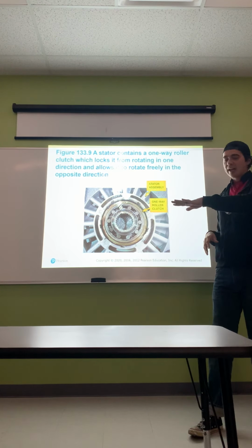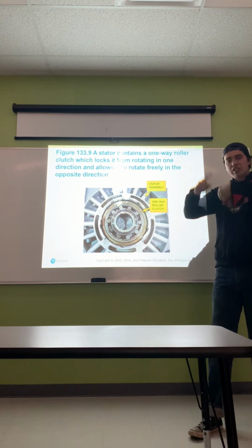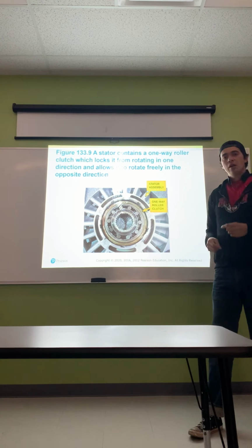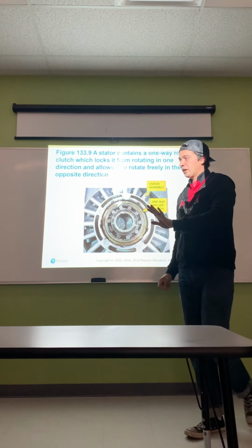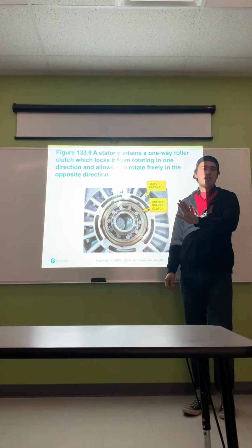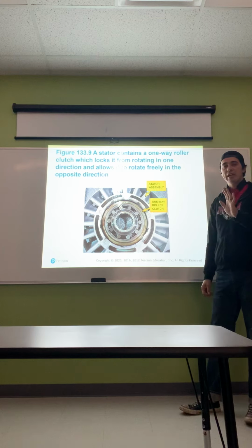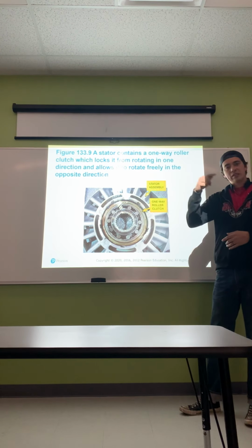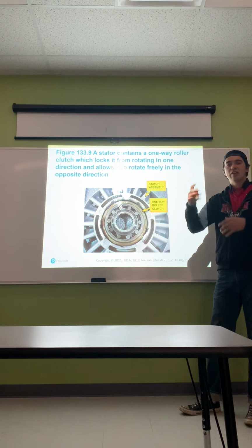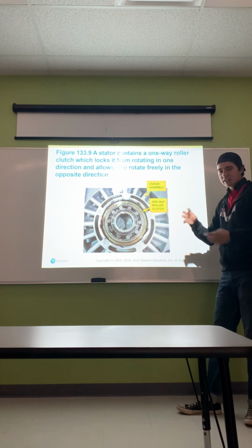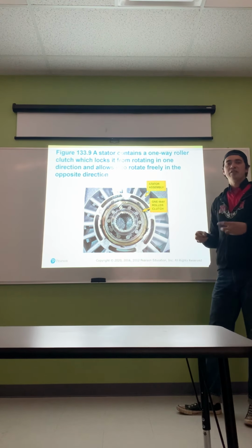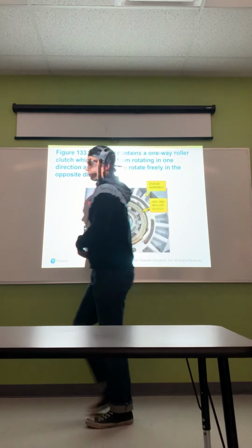So now we can sit at idle, not enough energy to move the engine or to move the vehicle, but just enough to where you can actually step on the brake and hold it and not kill the engine. When you think about an automatic transmission, when you let your foot off the brake, the vehicle starts to roll. That's that slight energy that's being created by the actual torque converter rotating and sending energy through the transmission, but it's not enough to actually stall the engine out.